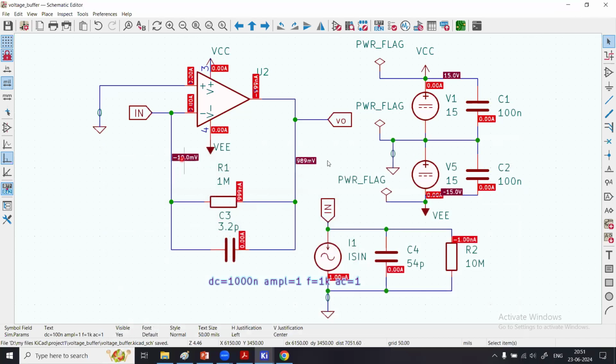Okay. So for a high-level current of 1 microamp, we can ignore the effect of offset voltage, but for very small currents, if your sensor current is pretty small and we want to actually detect those minute changes, look at the offset of the op-amp, the kind of role it plays, right? So that's it. Now once you see that R1 and C3 set the pole frequency, right?